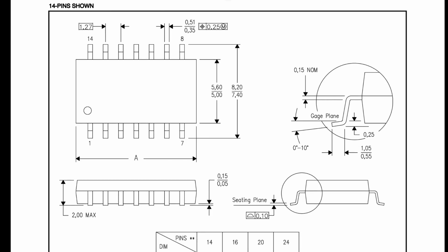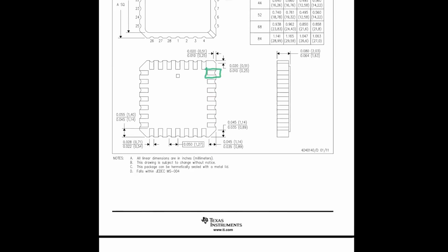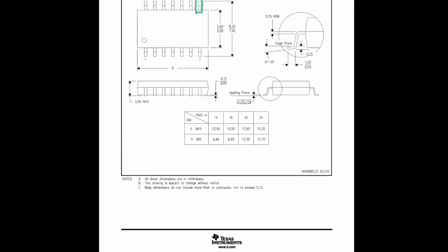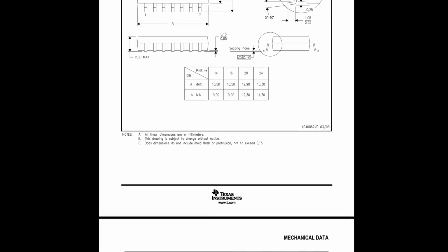There's our SO package. Once again, if you're designing a pad that sits on your chip like that, it's a standard SO package, but let's just assume that it's something weird you don't have the footprint for. You're designing your footprint, then by all means, you've got to design your own footprint for this. Some packages, like Altium, for example, PCB layout packages, might have an IPC footprint wizard, and you need all of the information contained in here. It'll have a common format. It'll ask you for all these particular widths here, your package width and stuff like that. So if you've got an SO package wizard generator that generates a footprint automatically, you just need to know this information, and you can get that from the data sheet.